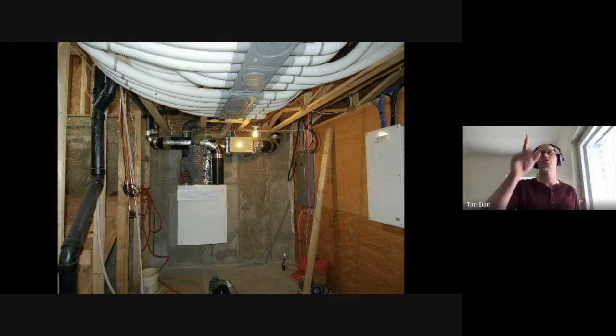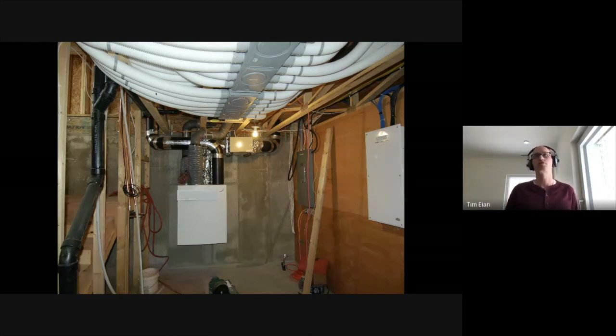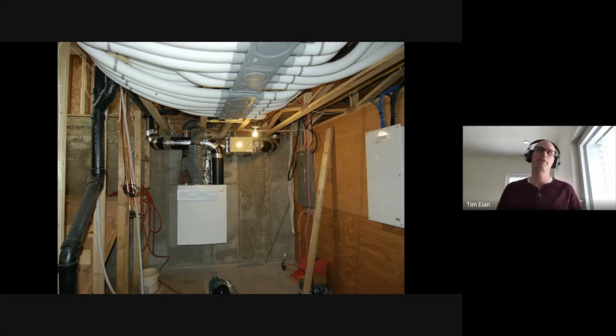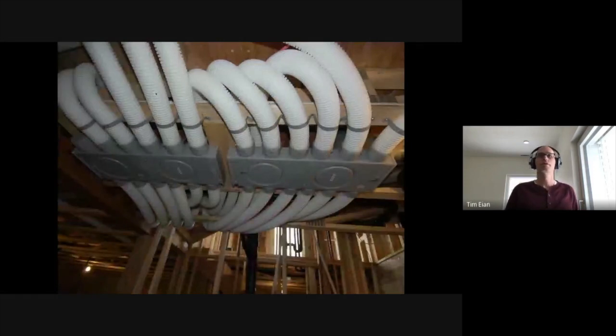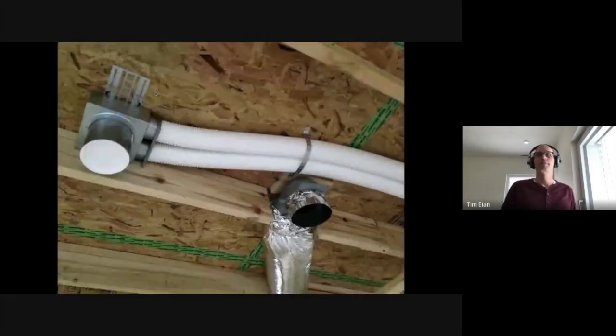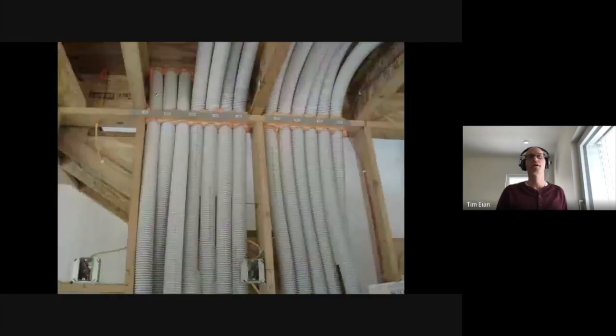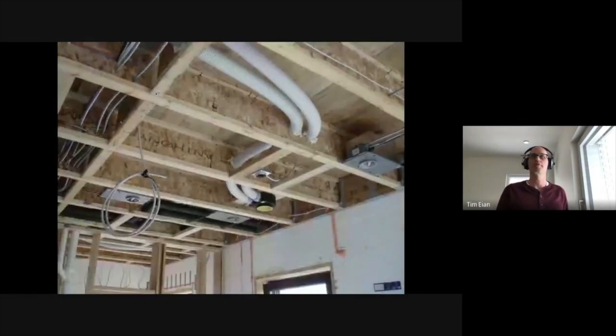And in this project, those gray boxes you see in the foreground on the ceiling are the manifolds. So basically, the air is being supplied to a central manifold, and then from there, home run to each room and return from other rooms. Generally, you supply to living and bedrooms, and you return from kitchen and bathrooms. Here's another close-up. These systems are now readily available in North America. Thankfully, that was a bit of a journey over the last 15 years, but they're basically everywhere now. There's just another version of the same thing.